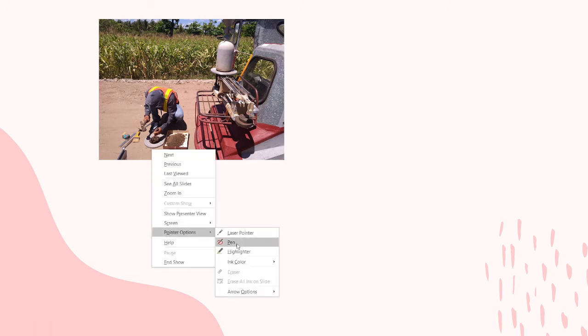So in my previous work, I was able to witness the conduct of the sand cone method. So in this first picture, you can see that the hole is dug in the compacted soil. So you can see the base plate and then the hole is being dug. And then this is the soil excavated from the hole.